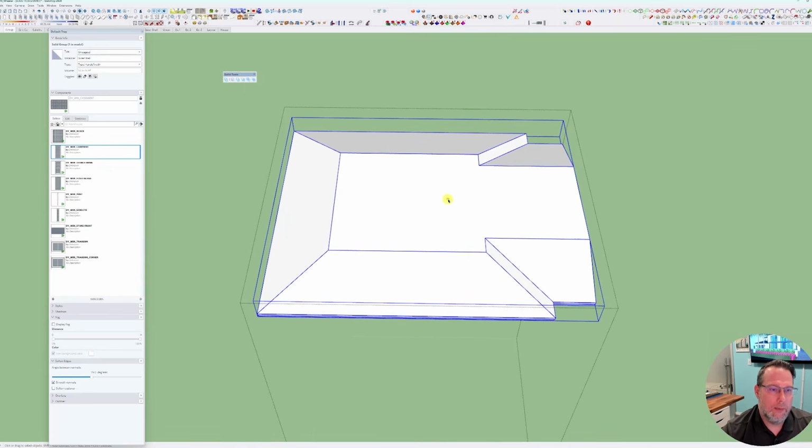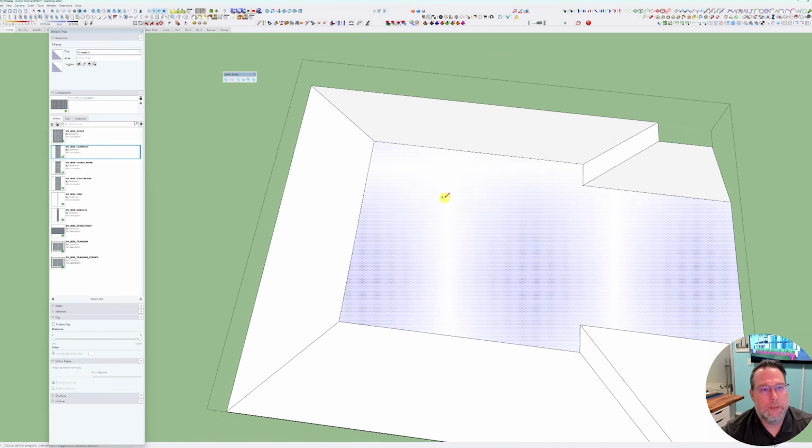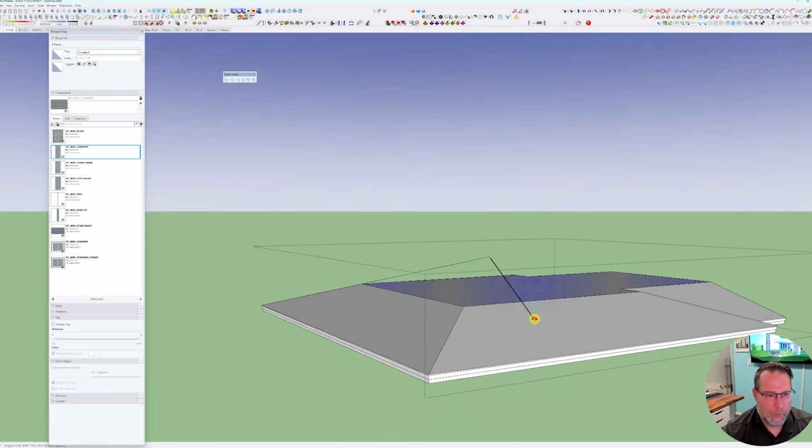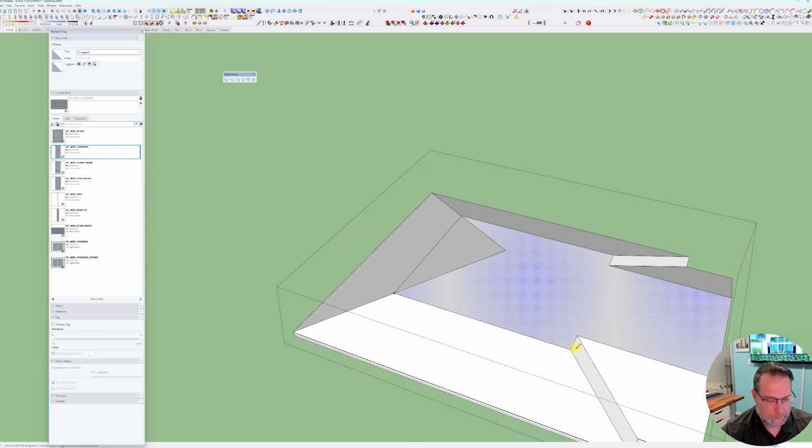So now if I double click and I want to edit the loose geometry, we're simply going to start drawing a line, so I entered point 1. Now I'm going to start kind of going backwards and hold Shift, which will lock me on that inference. And I'm going to come across and tap the other side, and that will give me my peak of where those two would intersect, and come down and draw.